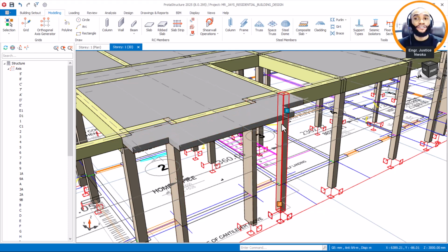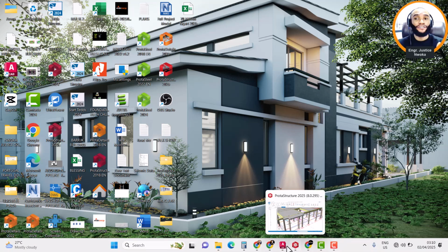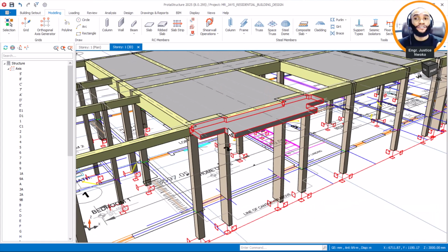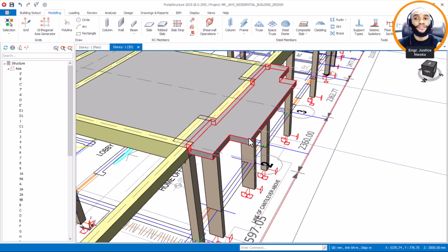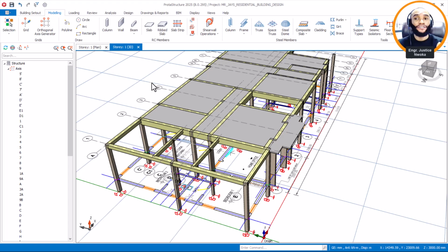So we will then apply this cantilever load around this place, because if you look at the 3D view, you can see that it has this slab edge here. As you can see, the edge here has a little bit of dwarf wall, which is for the balcony. So we need to apply this load too, and also this load here on the cantilever slab edge. That's fine. So back again now on this place here, so you can now see it here. So we also apply the load and then floor load as this. You can see it right now.